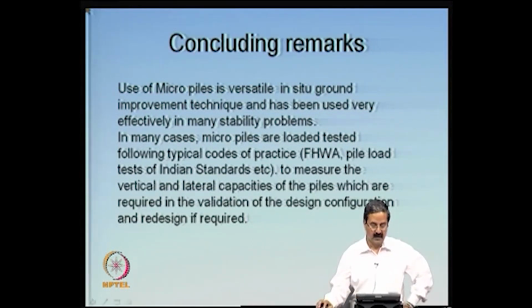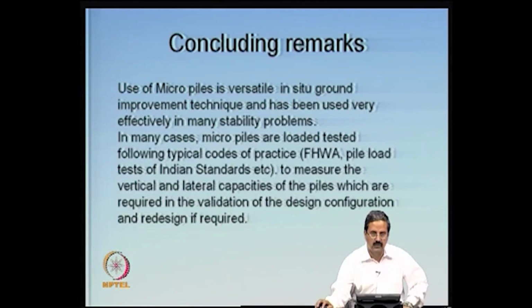As I just mentioned, it has been very effective in many ground improvement problems. Here I assume some numbers to calculate what should be the micropile capacity. You may design the piles using standard practice, but the best is to do the testing, a lateral load test or a vertical load test. One can do either using the same testing setup, like we know how to do a pile load test.